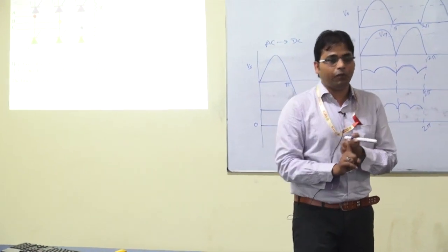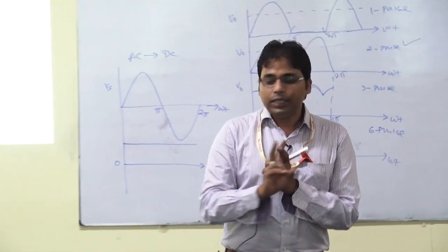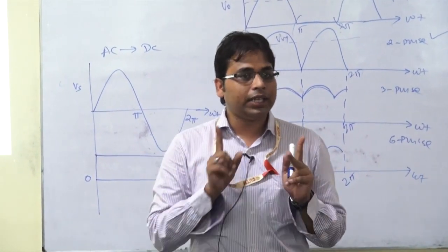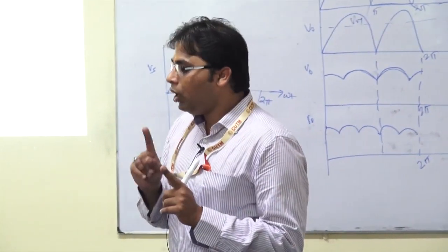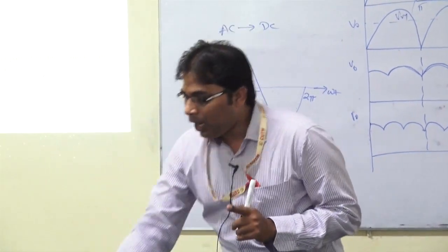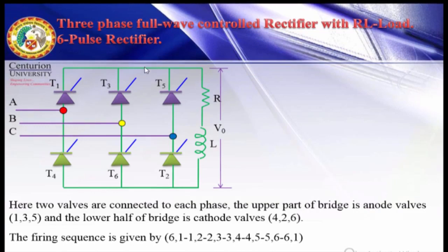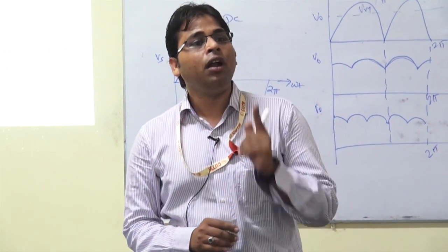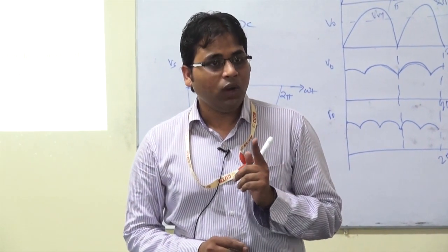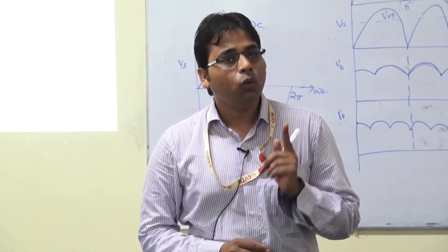Before going to the waveform, first remember that 2 thyristors will conduct at a time, one from the upper half and another from the lower half. One thyristor will conduct for 120 degrees.